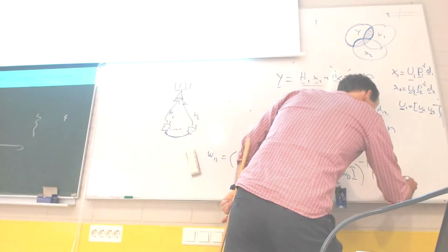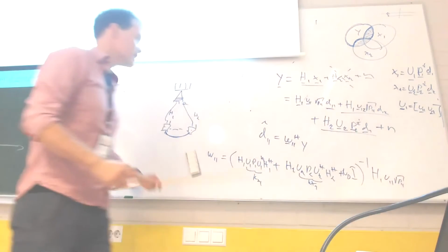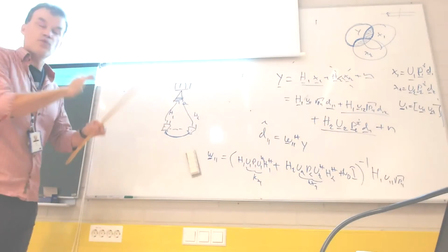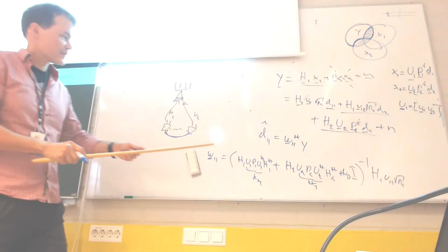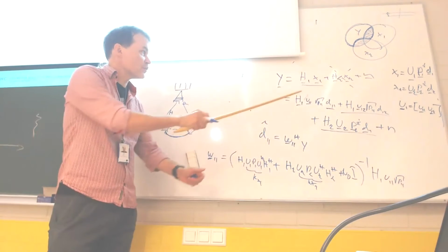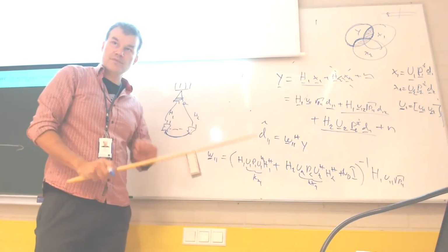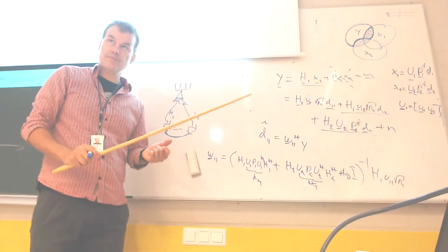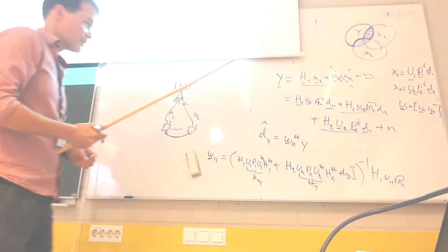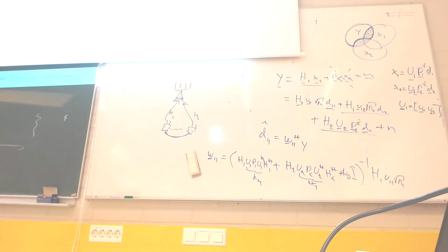U11 square root. Right. So this would be the MMSE. It's the true MMSE, right? Of course, from the SINR perspective, we have the other version where we exclude the own term. From the SINR perspective, it's the same. You have seen that from the first homework. So everything extends. It's not just an extension of the single point-to-point case, the single antenna transmitter case.